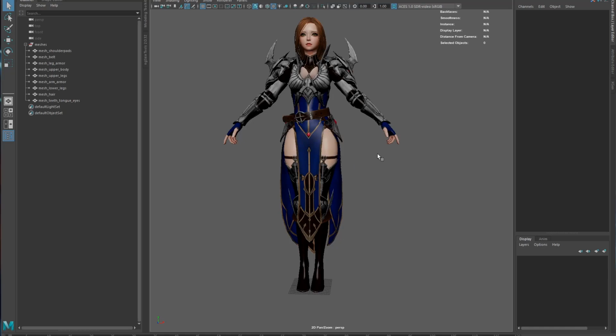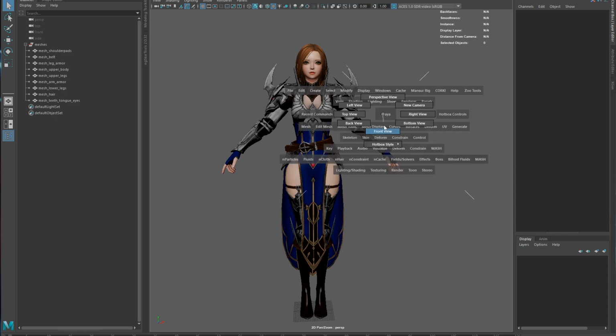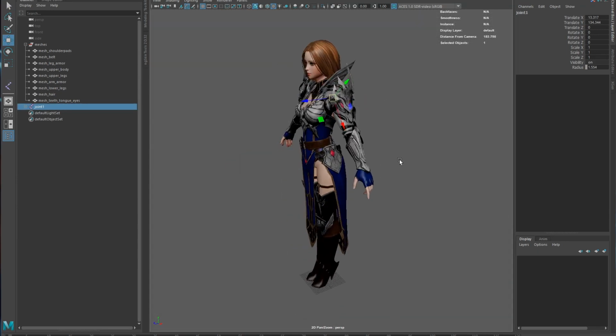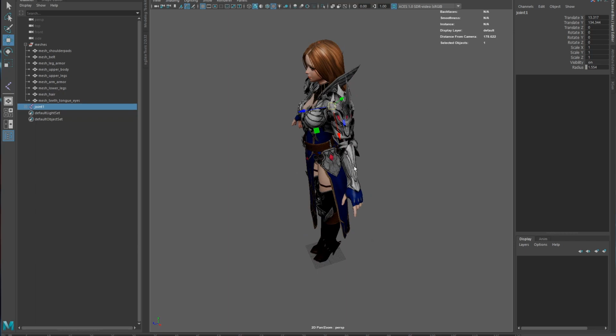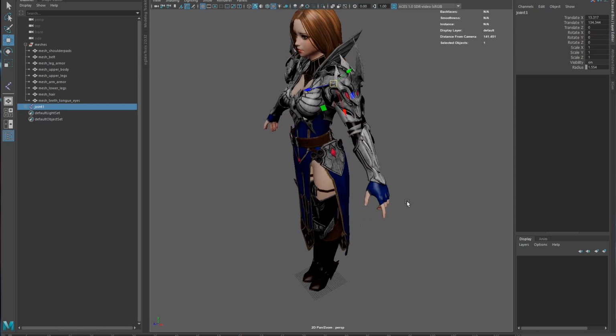Okay, so in this video, I'm going to go through and talk about joint placement fundamentals. Your joints are the foundation of everything going forward, and so it's good to understand how best to place and orient joints. A lot of people, when they are placing joints, might go into an orthographic view and just do something like click, click, click, and that's fine, but personally I feel like I'd have to do a lot more editing in this way of doing it, and I feel like it's a little bit more error prone in introducing issues into my placement.